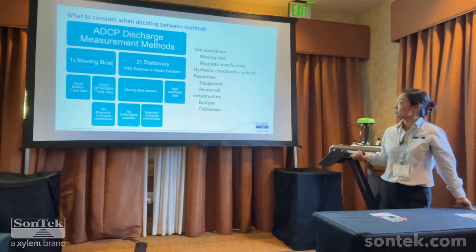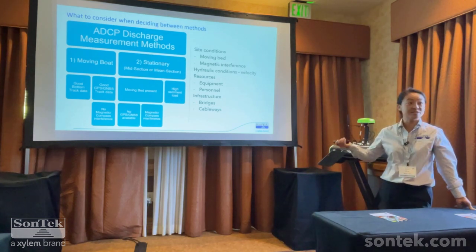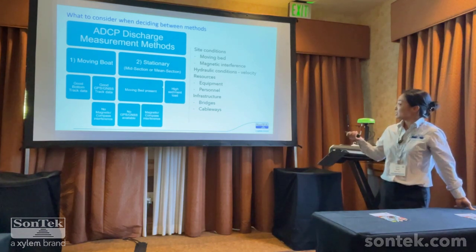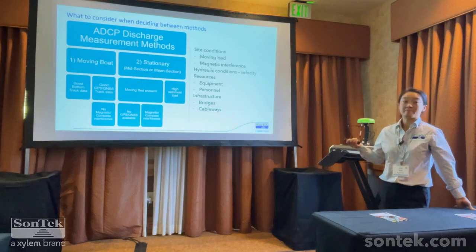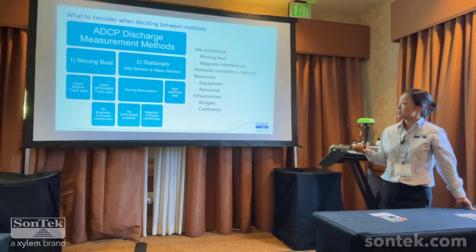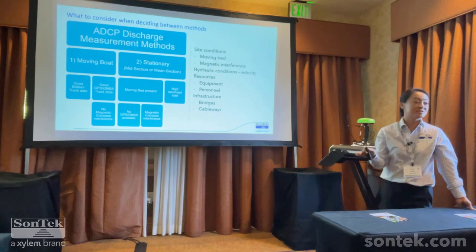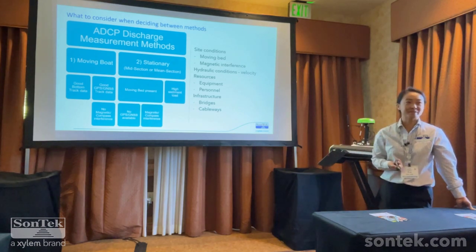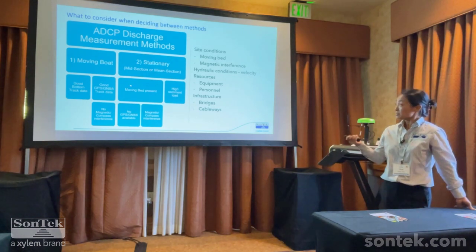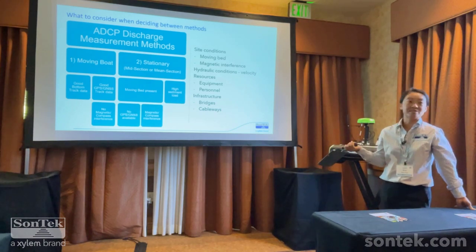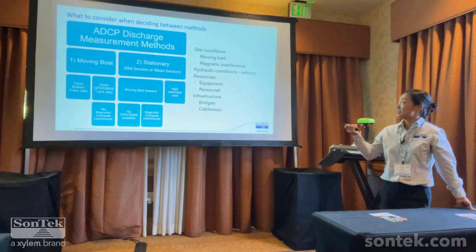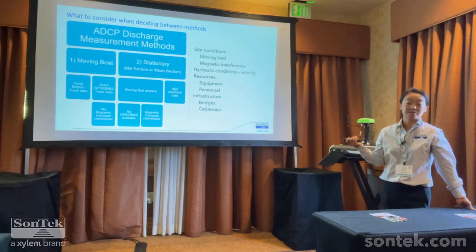We see most frequently people want to use a stationary method when they have sites with one or more complications. This includes something like a moving bed. I will define some of these terms in a little bit if they sound unfamiliar. But if you are using a bottom track only system and you have a moving bed situation, oftentimes stationary is the way to go. So you don't need to track the bottom or anything like that.